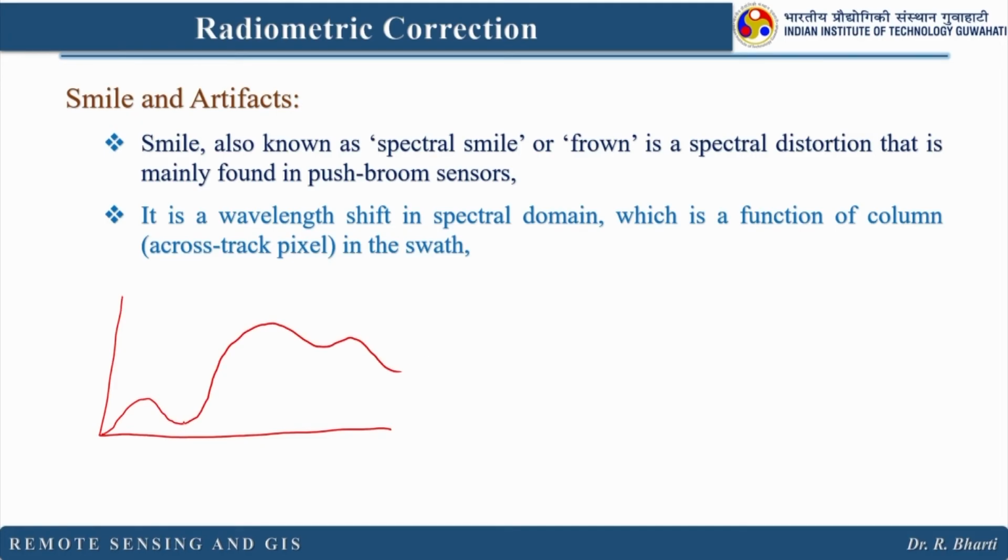So which is something like this. This is 0.7 micrometer and this is 2.5 micrometer and this is 0.4. So in green wavelength, this is the maximum peak which we are able to see, but this area we cannot see. But in measured spectral response, we can always find what is the behavior of that particular material in other regions. That is the advantage with remote sensing.